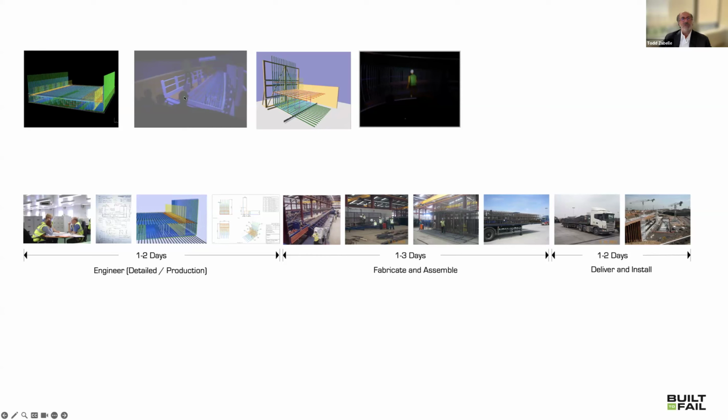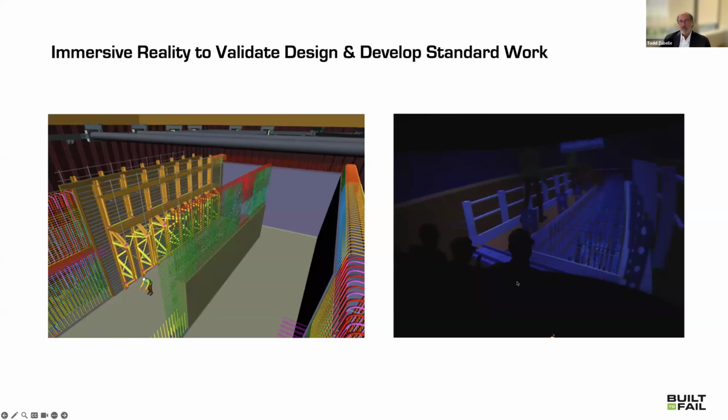We took advantage of immersive reality, so we went into immersive reality centers. We had people in there that were rebar fixers or iron workers, or rebar benders as they're called here in the U.S. And they sat in there with the structural engineer, and they would look at things like, look, I can't pull a 50 millimeter bar through there, but give me 5 10s or 10 5s or something. And these guys were doing the design to get to exactly what needed to happen using immersive reality. It was incredible to watch them, right? A structural engineer talking to a foreman, and both of them saying to each other, I never knew that. Oh, really?